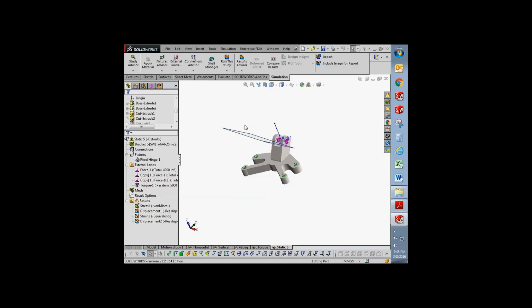They have SolidWorks Premium, where it has a nice UI for setting up all the load cases. It'll run each load case. But also the benefit of using load cases is you can do something called secondary load cases or secondary combinations, where you can say this load and this load act together, what happens? If this load and this load act together, what happens? So you can do all these combinations from just the primary load cases. When running it, it's going to do the primary load cases and just add up for all your secondary load cases, so it's faster. And then it's got some nice post-processing to track the factor of safety for each load case. It's got a nice table so you can compare all that in one place, so you don't have to switch between studies.